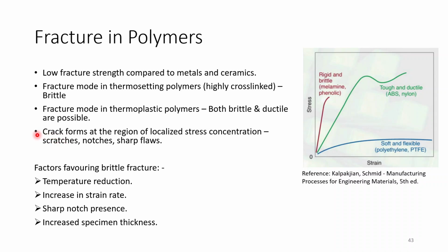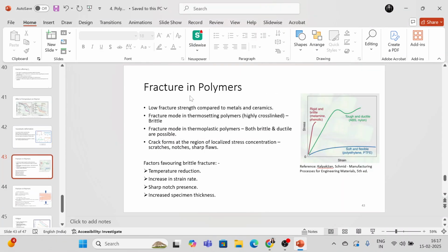In this case, cracks form at regions of localized stress concentration, and scratches, notches, and sharp flaws which already exist can also act as stress raising points.